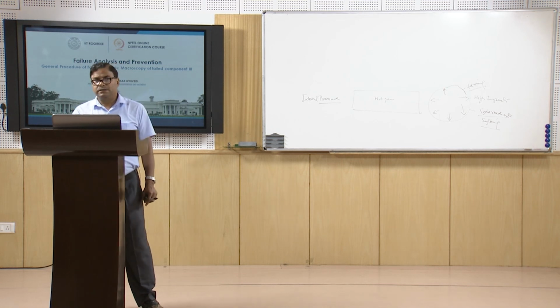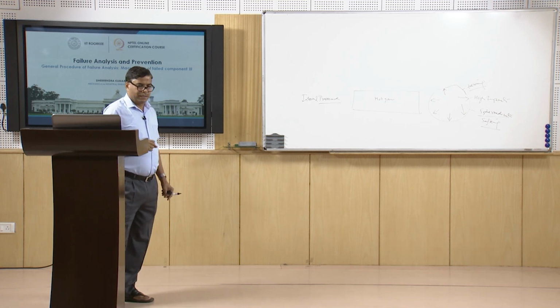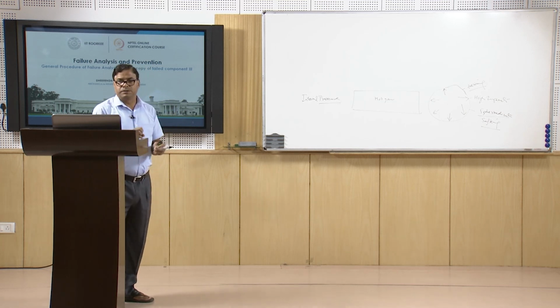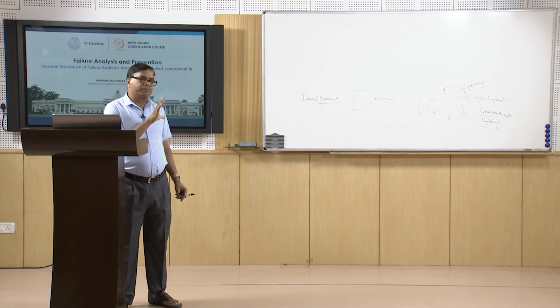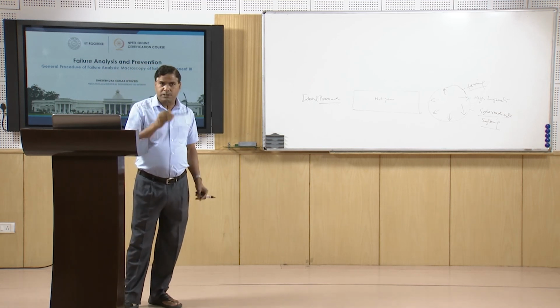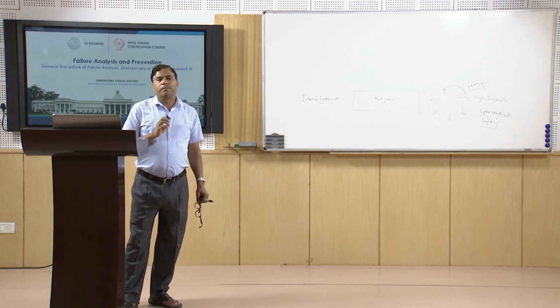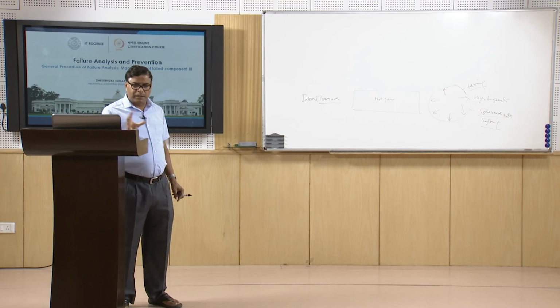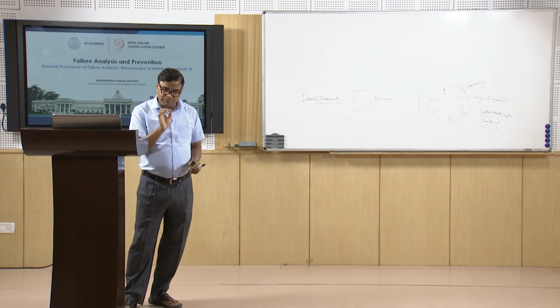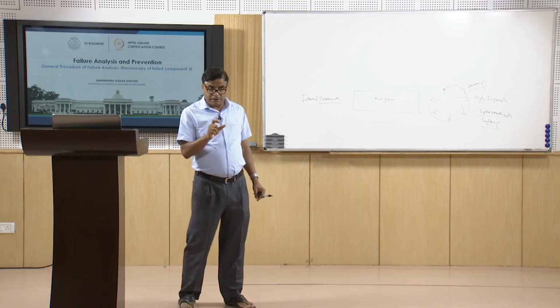Then we know that whenever the component is produced by casting, for cleaning purposes we do sand blasting or shot blasting. Sometimes shot blasting and shot peening are also carried out to improve the fatigue life of the component. Cracks also appear when the component is subjected to cyclic loading, and these happen due to localized slip phenomena at the surface.